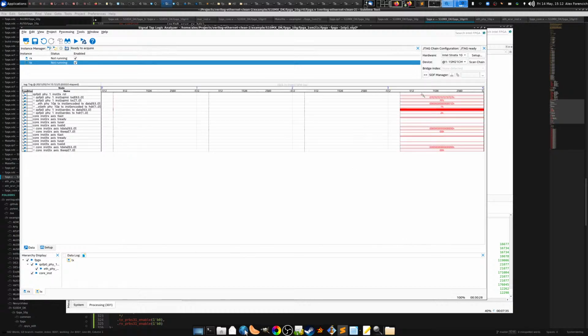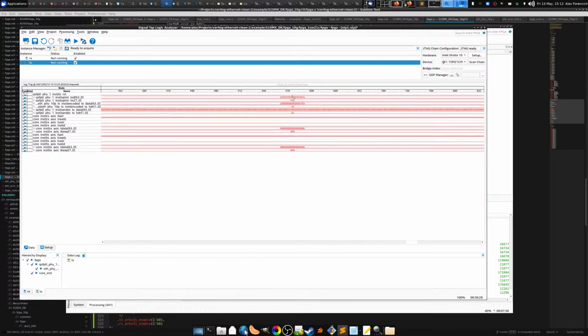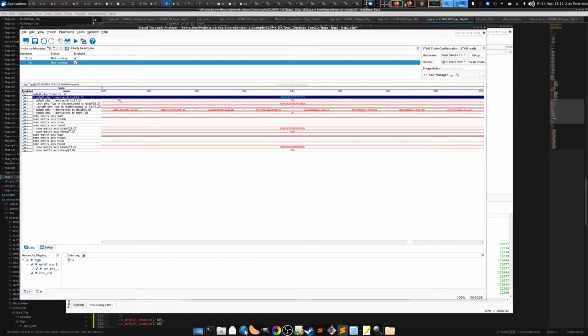Single shot capture. Okay, so on the TX side things look fine, right? On the XGMII interface, when nothing is happening on the link and it's not actually sending data, it's continuously sending idles. So this is sending 07070707, which are 8 idle control characters. All locations are marked as control characters. The PHY then encodes it with block type 1E, and there's the header, right? And then it gets scrambled, and that's what actually gets sent out over the wire. This is the scrambled stuff that gets sent out over the link.